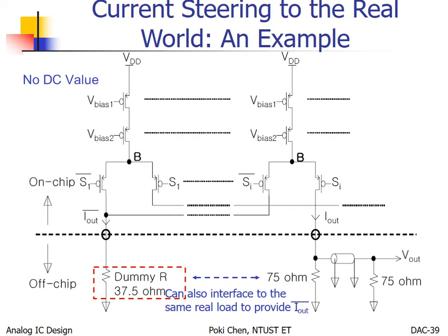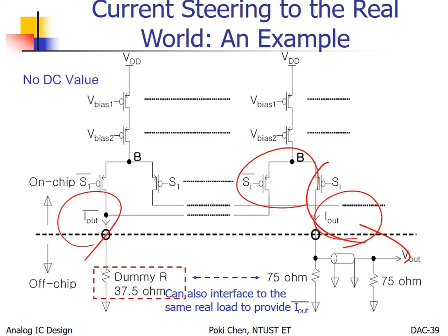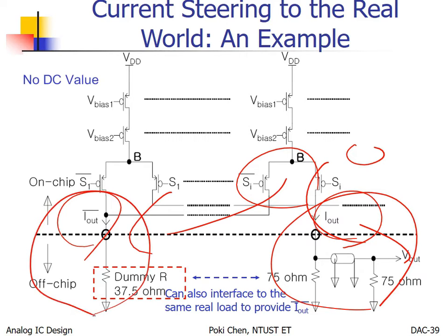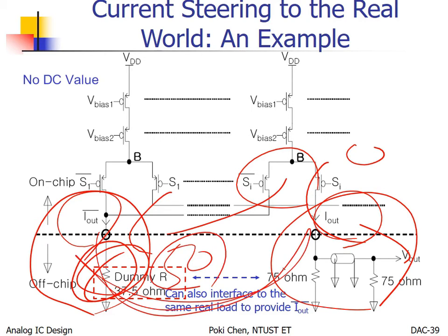Anyway, again, this is something for differential output. You have positive output, negative output, so switch to the right or to the left. It depends on the control bit, the value of the control bit. And you need to make sure you will get real differential output, right? So everything to the right and to the left should be exactly the same. You have the so-called termination. We need a terminator, right, to provide usually overall 50 ohms between all of them.